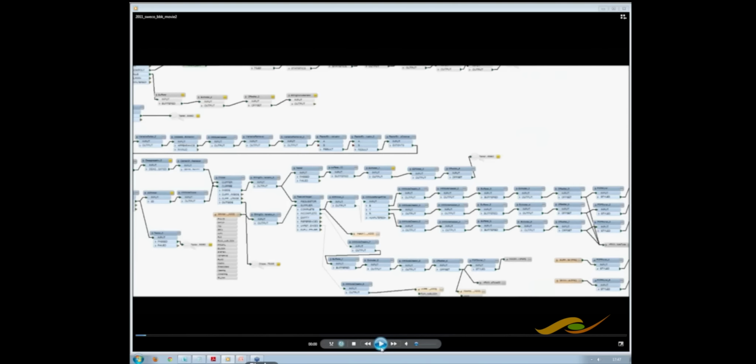We're actually working with the accuracy now, and what we are using are benchmarks that already exist in the power plant. There are small copper plates all over the plant that were put in there while they constructed it, where we have the actual points. So we're using those to control the accuracy of the model.